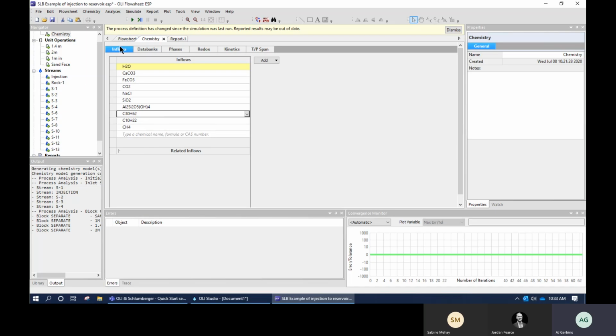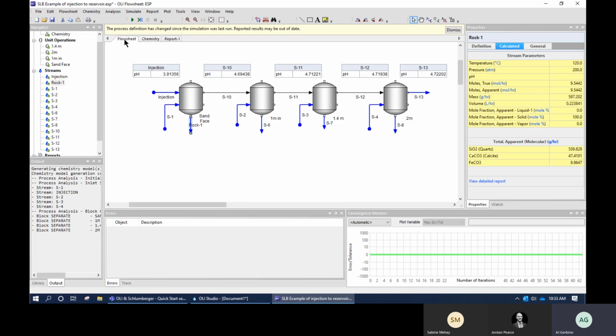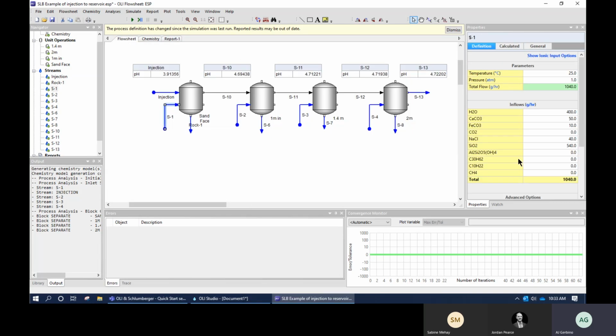Now that you're right, it'll be a little bit cooler what we can do here. Because then what we're going to want to do is add the hydrocarbons here, right? So we can see the partitioning. And also, once we start adding the aluminosilicates, and if we start adding some HF or nitric or some of the other acids, we can start seeing the dissolution of the aluminum, or the reaction of the aluminum with the fluoride in this system. So I'm going to leave the aluminum out right now, but I am going to put in the hydrocarbons, 100 grams of each.